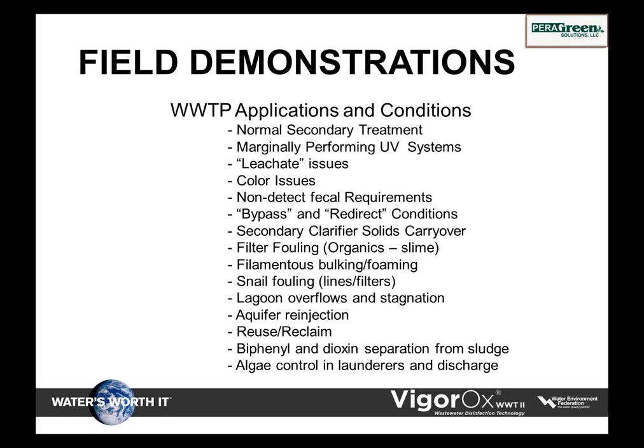But then you take a look at some other places. If you have marginally performing UV systems, this can enhance the performance of the UV. We've seen places where UVTs drop, and by feeding PAA, you meet the permit levels, and you can discharge the water.